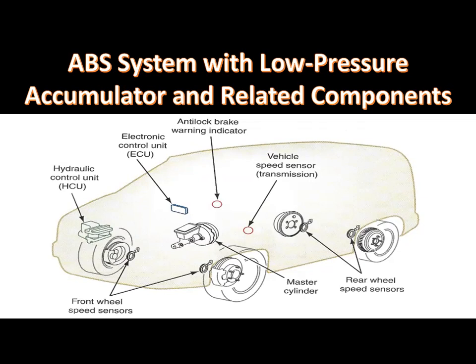This pump forces brake fluid back against the master cylinder pistons and onto the isolation valves. This action maintains brake pedal height during the anti-lock mode. In the anti-lock mode, the driver may feel pedal pulsations and a limited brake pedal fade followed by upward brake pedal movement.